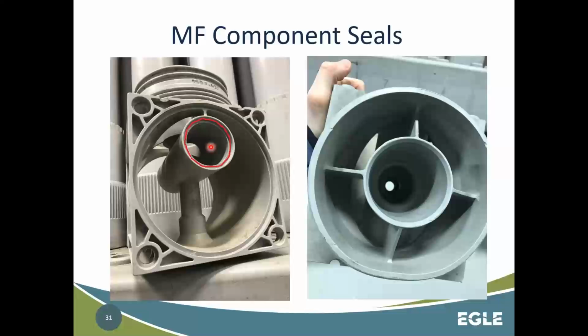So you actually have your filtered water pipe inside of your raw water pipe, which I don't particularly like because that's a common wall. But you'll see where I highlighted in red here, you would have a seal or an O-ring there. And that's another failure point.